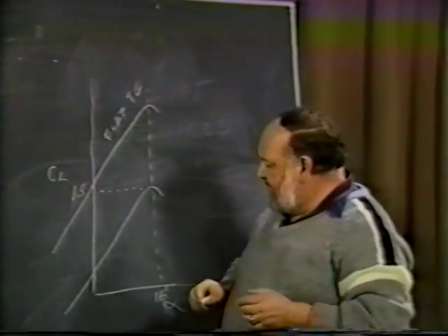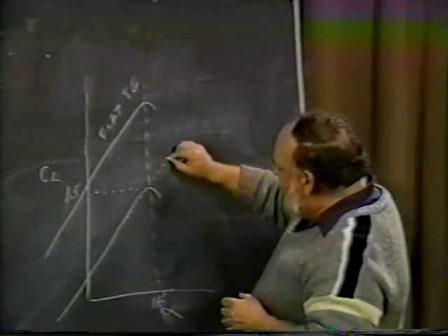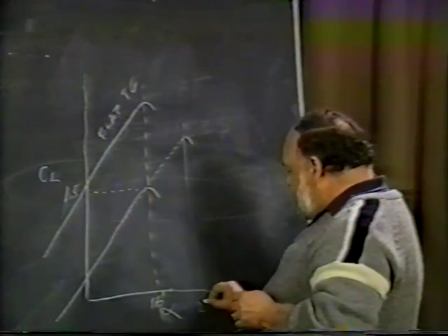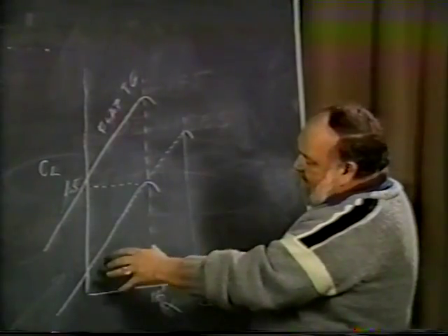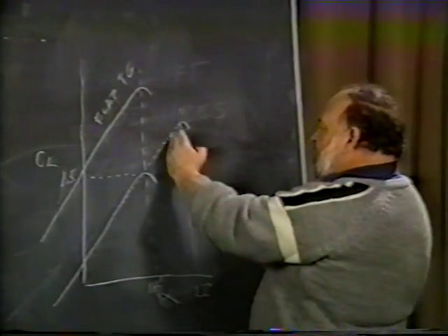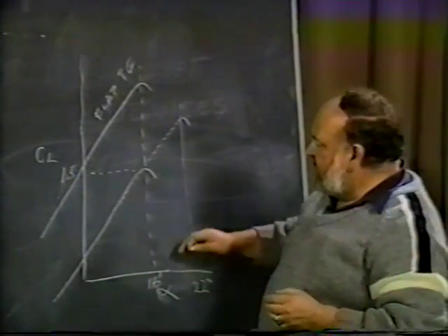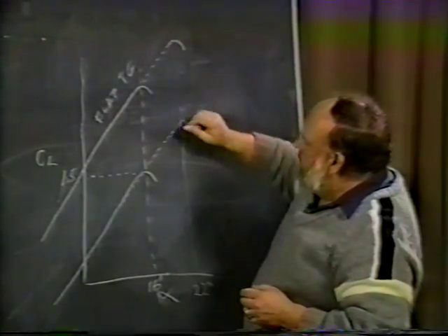and the leading edge, on the other hand, assuming you don't have flaps on it, will take this original curve and extend it to maybe 22 degrees angle of attack. So without flaps in the back, if you put a leading edge extension, you're going to take the standard lift curve slope and just continue it on to a much, much higher angle of attack. Obviously, if you use both together, you're going to have this effect.